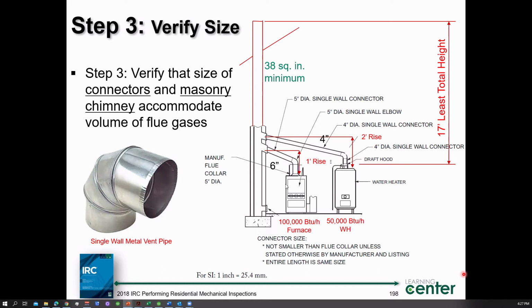You would use a manufacturer's chart, Don, in the same fashion that we just went through. They have charts that you actually use to size the stainless steel chimney liners and the corrugated aluminum chimney liners. You don't use this code methodology for those chimney liners, no.